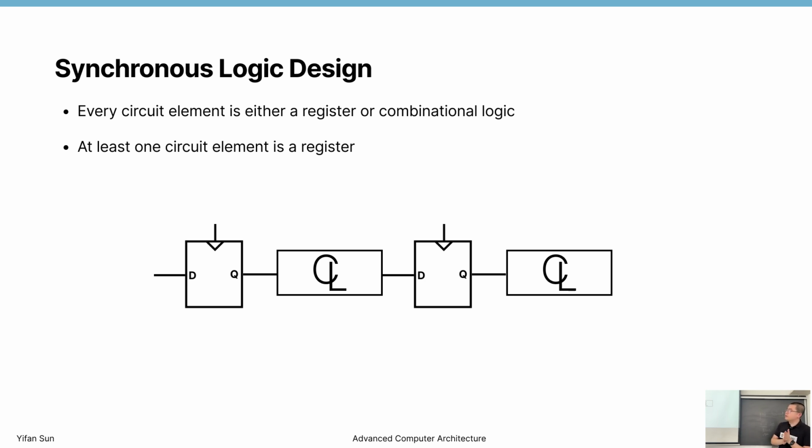Every element is either a register or a combinational logic. So we have registers, we have combinational logic, and at least one circuit element is a register. If it's pure combinational logic, we don't call it synchronous or sequential logic design.